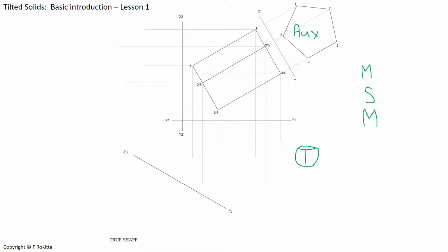And you can find very good tutorials on YouTube made by teachers and instructors explaining the principles and construction of points and lines, which is the prelude to solid drawings. Therefore, we also need to understand our rulebook that teaches us that the XY separates different views from one another. And if we understand that rule, we also know that the projection from one view to another over the XY must be at an angle of 90 degrees to the XY.